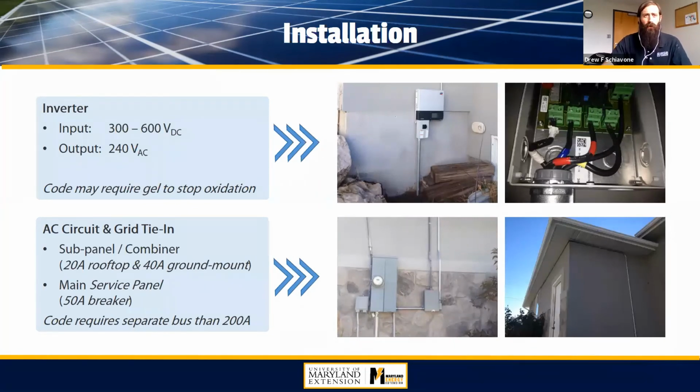Now, where the electrical goes, it travels all that distance across the property back to the main residence, and the inverter here is receiving anywhere from 300 to 600 volts. In previous sessions, like I said, we learned how to size this system, so you can revisit that. This system receives 300 to 600 volts DC direct current, and then converts that to 240 volts alternating current.